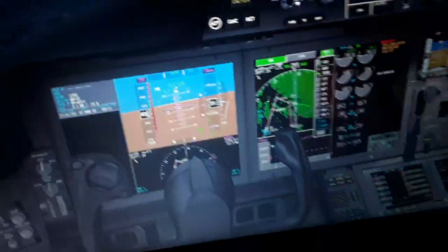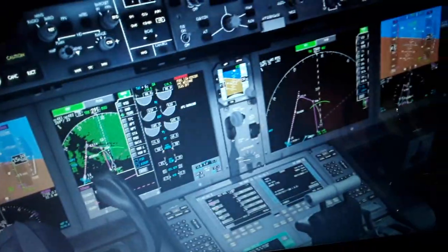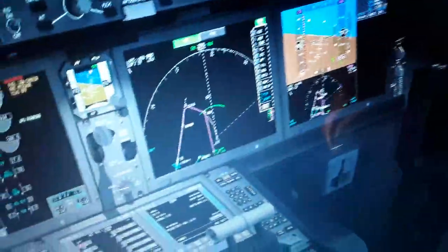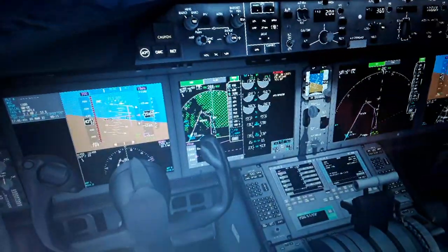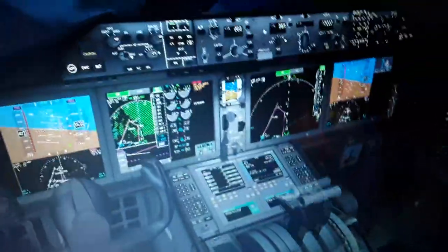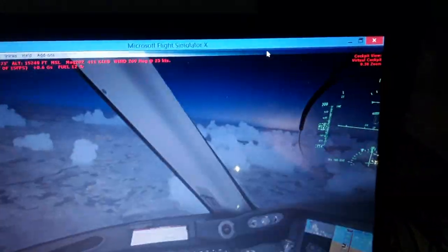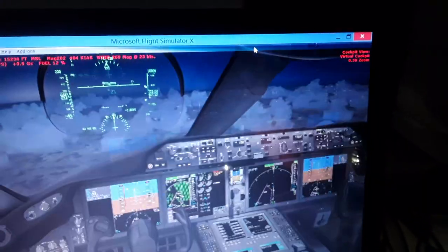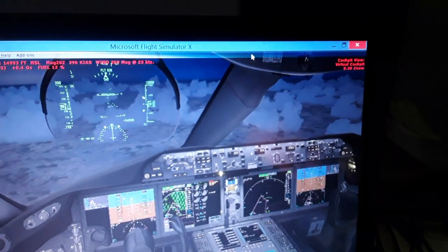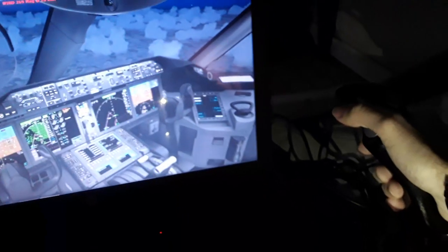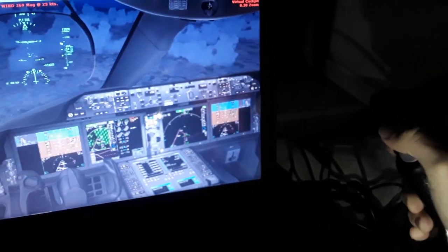And we have 5 more minutes for approach and landing over here. Leveling off, throttle used to the idle position here as we are descending. Need 4 more minutes for descent and approach here.